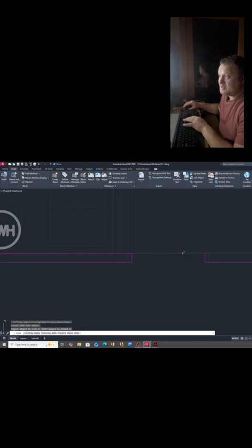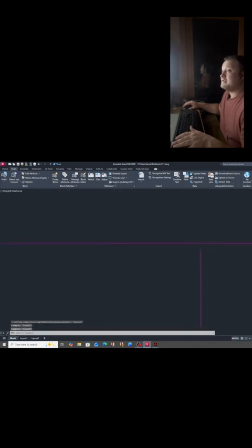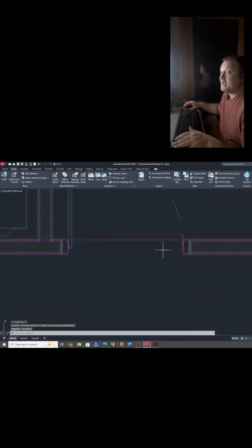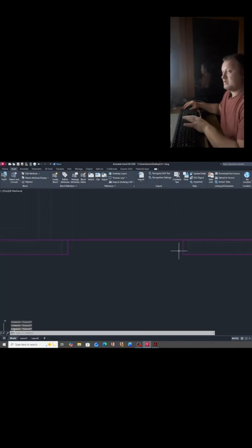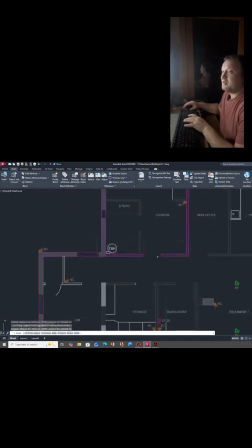If I go here, it wants to delete the whole line, which tells me that we're not touching. So I can zoom in and see that we're missing right here. So if I bring this up and then get it so it stops at the line, now we have 2 points that we're saying that we want it trimmed between these 2 points. So I'll just type in TR, and there we go.